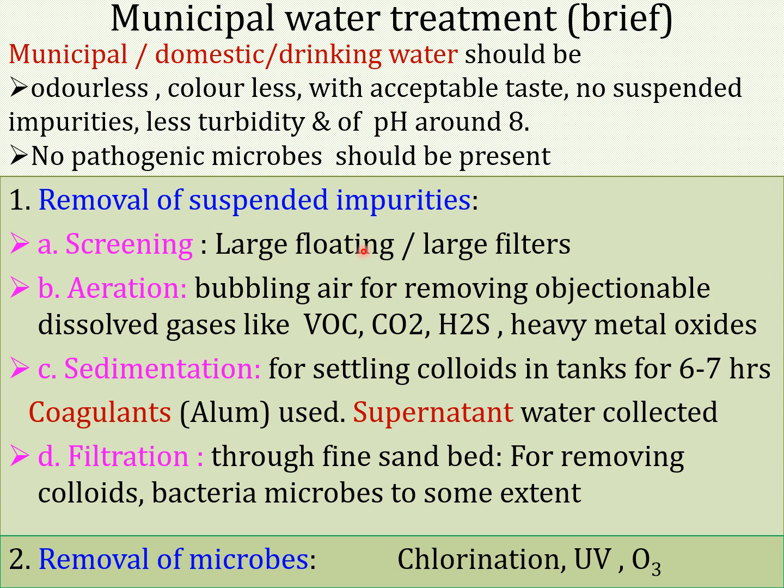for filtration. That is the fourth stage. The first is screening, then aeration, then sedimentation, and the fourth one is filtration. We send water through the fine sand bed so that the rest of the colloids, if any, will be removed, and also to some extent microbes and even bacteria will be removed. Well, this water is finally sent for removal of microbes, the disinfection process.